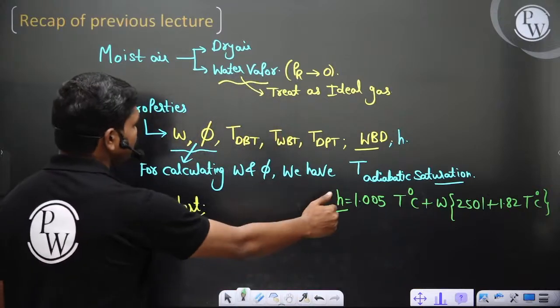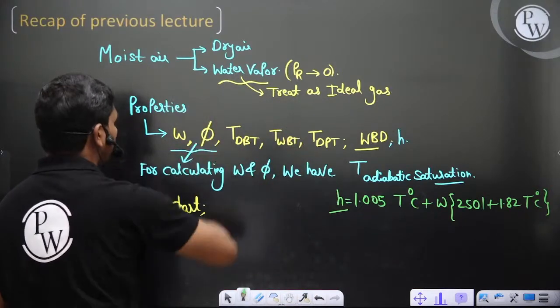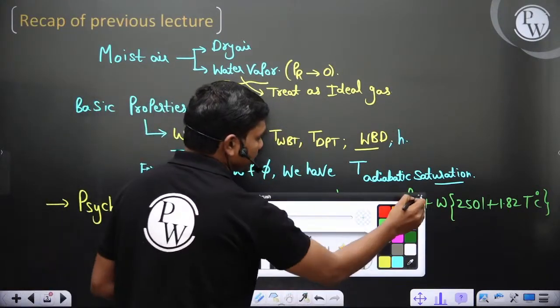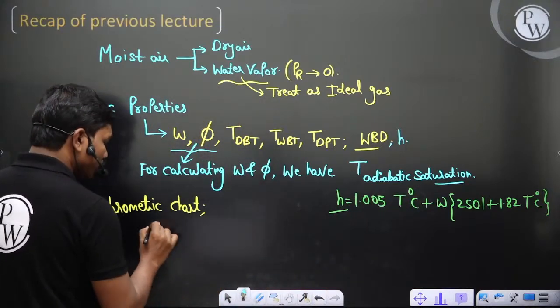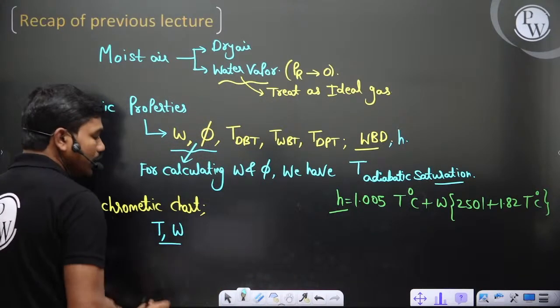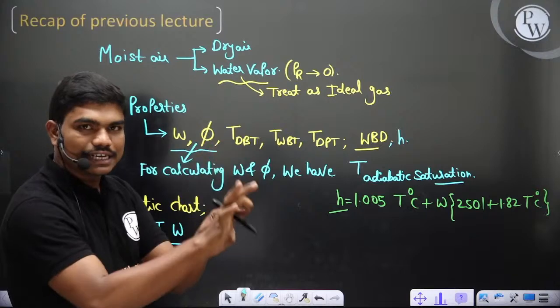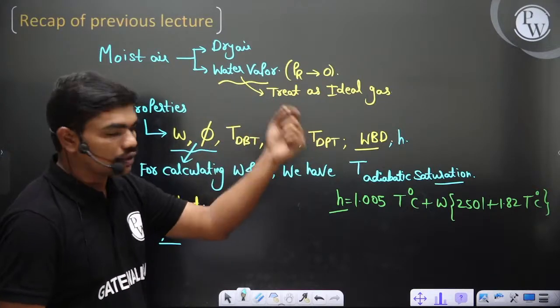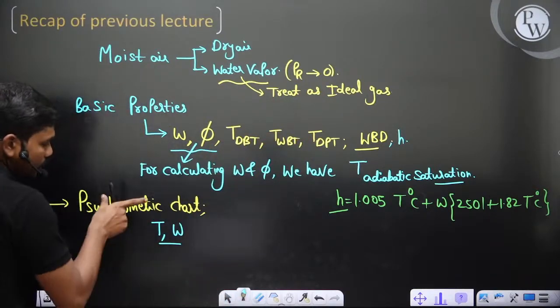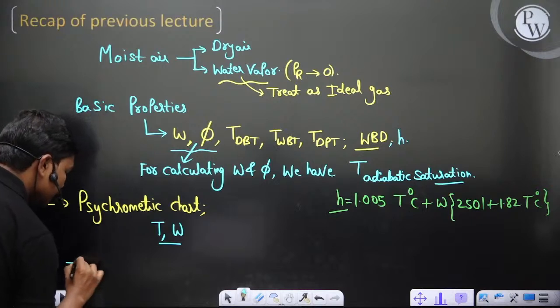Okay, so this summation gives you the specific enthalpy of this moist air. And in case of psychrometric chart, we have seen basically if you spot T, dry bulb temperature, and omega, you can spot out different quantities like relative humidity, enthalpy, specific volumes, all this stuff you can point out. Okay, so psychrometric chart, and then we have seen psychrometric processes.